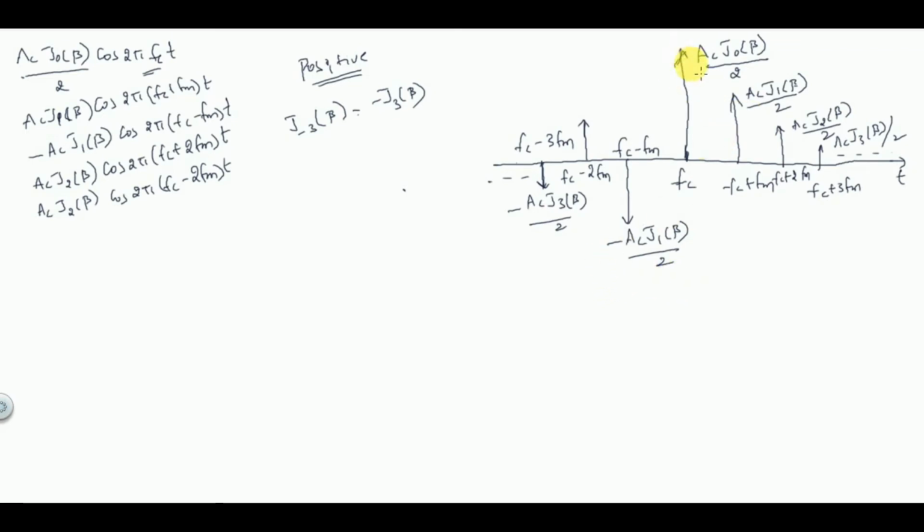If you observe here, why have I drawn decreasing impulse functions? The concept here is the first property. The third property of the Bessel function, which I have told you, I used in finding the power. The second property we used in the previous slide to write the standard time domain equation for drawing this spectrum. And now, to draw the spectrum, I am using the first property. What is that property? As n value increases, Jn of beta value decreases. So n value is increasing here: 0 here, 1 here, 2 here, 3 here. So Jn of beta value decreases. I have shown that decrease in amplitudes also. That is why the impulse amplitude decreases when n value increases. Right, now this is the spectrum.